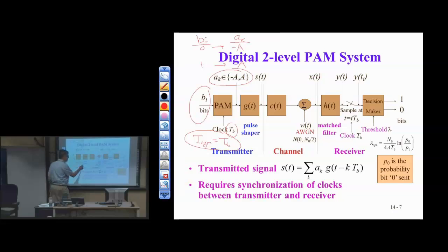So pulse shaping has two reasons: it makes detection easier, and it limits the bandwidth that we use. This pulse shaping filter is low pass in frequency selectivity. The channel is going to have memory, and we represent this with an FIR filter, a rectangular impulse response if you wish. Additive noise, historically called white Gaussian noise, which is fine. I tend to use spectrally flat, which is a little bit more right.